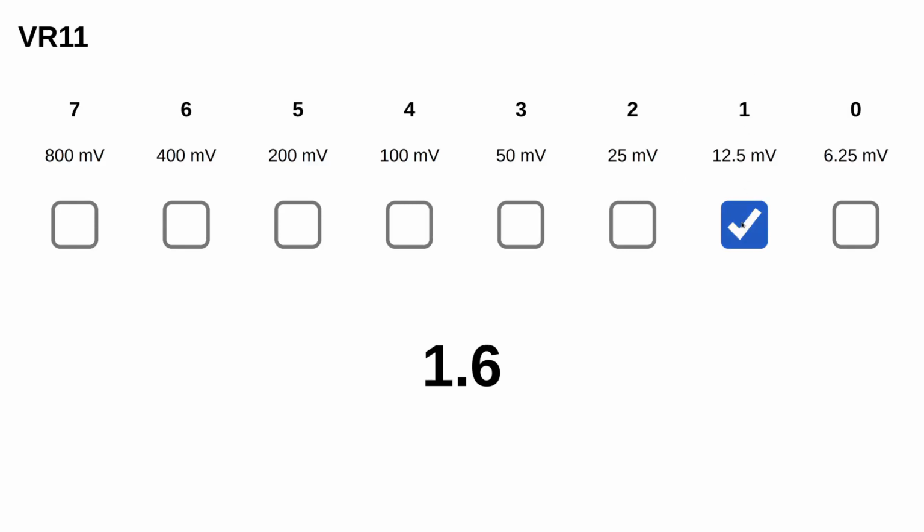And the other thing to note here is that when you're calculating VID codes, it's often just really nice to plan it out ahead of time and keep track of which switch corresponds to which vid bit. So one of the easiest mistakes to make is to think, oh, I want to get the vid for 1.4 volts, 0, 1, 0, 1, 0, 0, 0, 1, 0, 0.